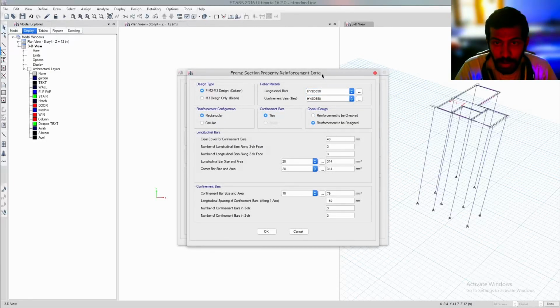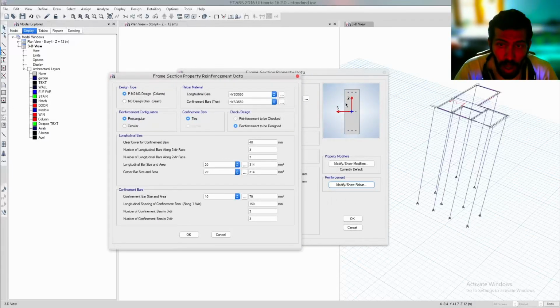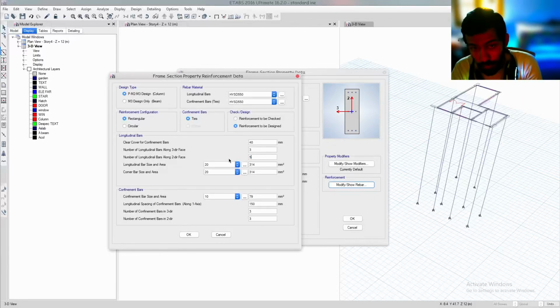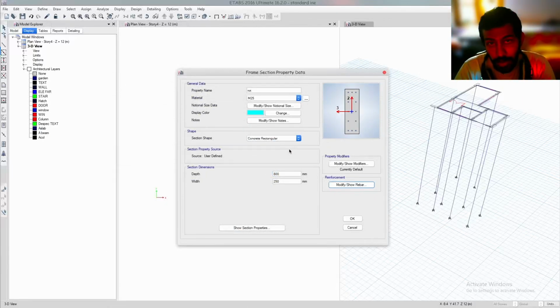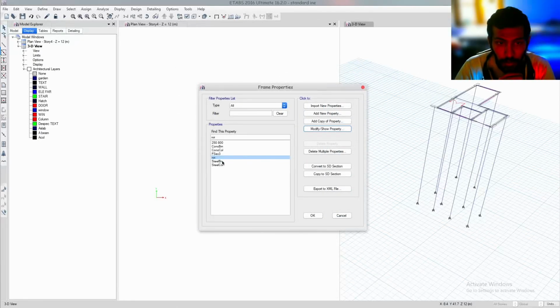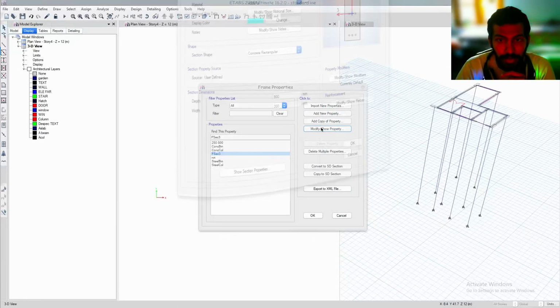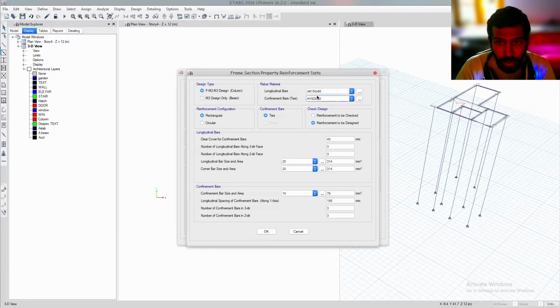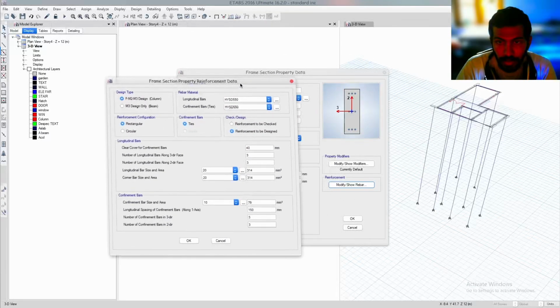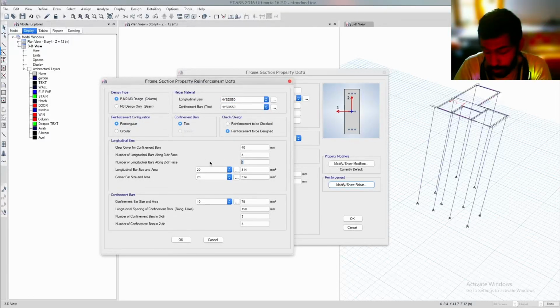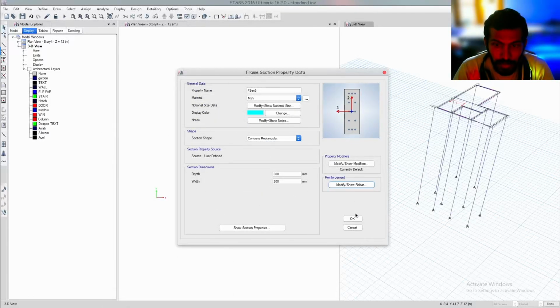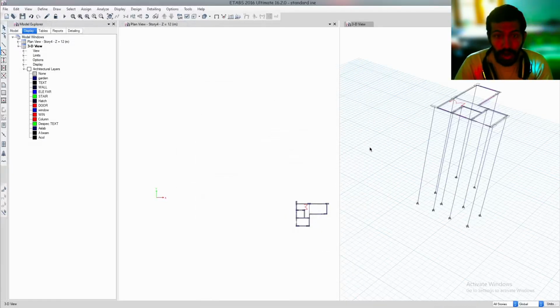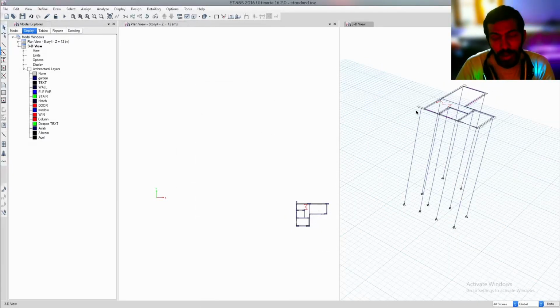Change the name, and I'd like to adjust the spacing and the number of bars in the 2 direction face, which is also 5. That's solely based on your experience. And we have a last section, 25, and change the property, which is HYSD. The number of bars in 2 axis should be maybe 5. I think alright, so everything regarding the beam is clear.